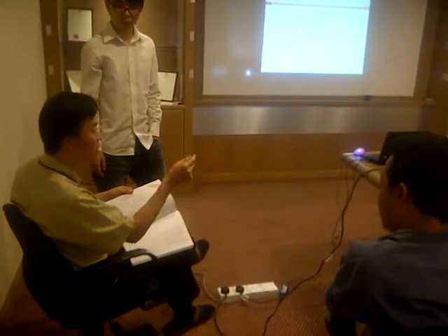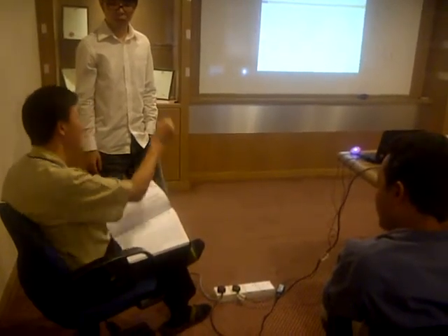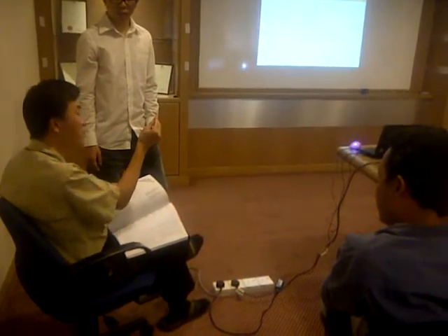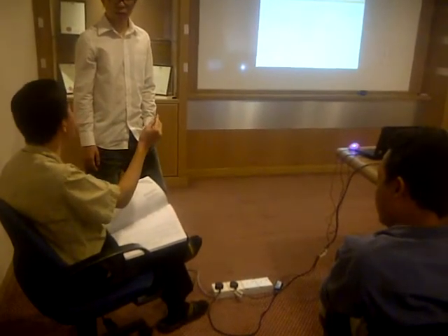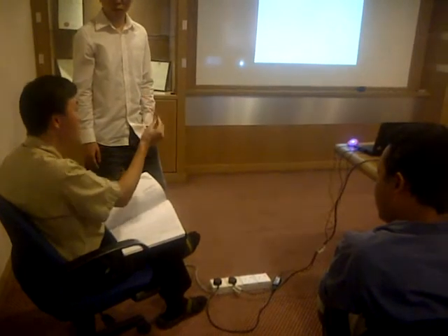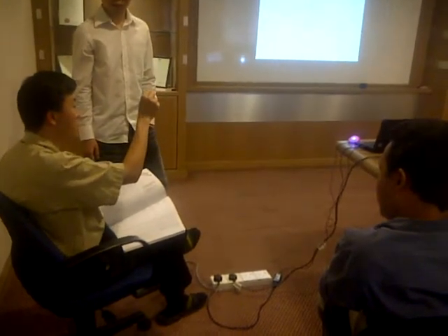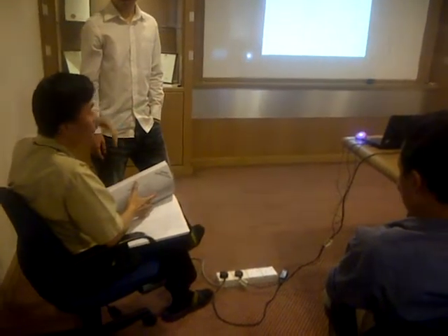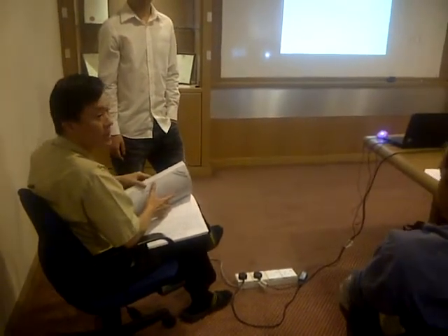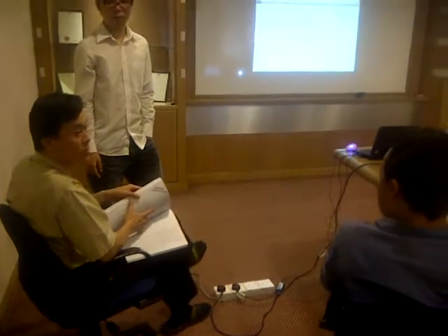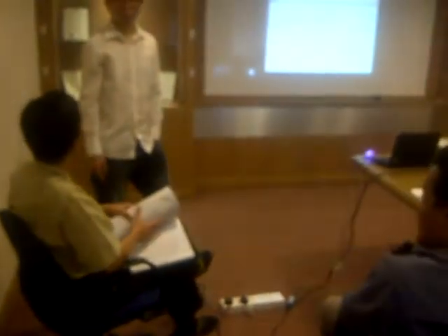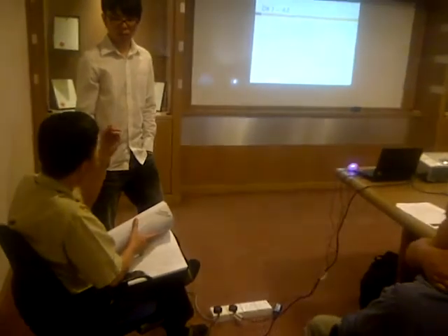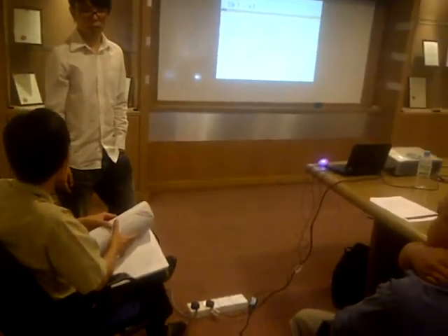When the cable is heated up, it brings the heat back to your DB, and in your DB there is a hotspot due to whatever thing. It can be a loose termination or whatsoever. So it will cause your RCD to trip intermittently. And this kind of problem is not easy to solve, because you don't know what exactly the problem is. Because of that, you have to design in the proper way.